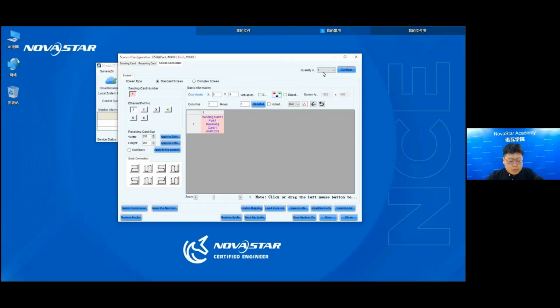We can see all of the ports of the sending card, because this sending card has 6 outputs. And this screen has 2 columns and 2 rows, which we set here, and we reset all. For each cabinet, I mean each receiving card, the size is 256 by 256. So we set the cabinet size over here, and we choose port 1. The screen connection should be like this, I mean, the main channel. So we have done the screen configuration. Over here, we choose to send to hardware.